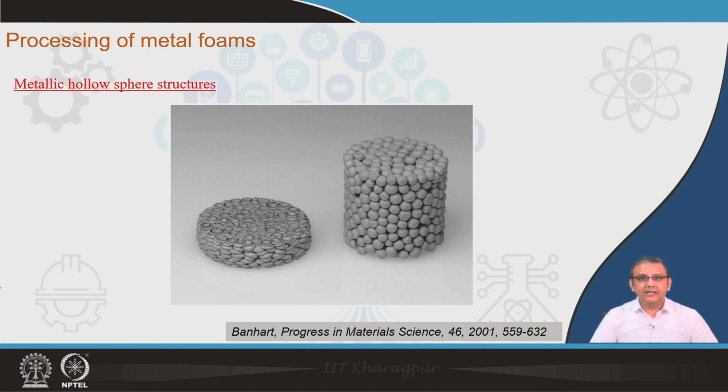As I already mentioned, this unique cellular structure has many advantages. One of the advantages is that the pore morphology and the pore size are very easily controlled and well defined, because they depend upon the initial size and dimensions of the styrofoam spheres. Another important thing is that these porous materials have different degrees of porosity. That means, these structures typically contain both open and closed porosity.